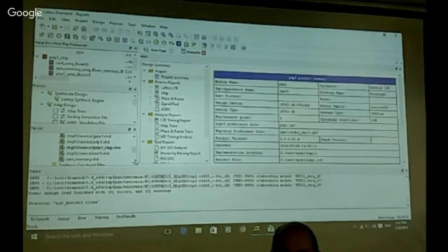For one thing, look at the instruction set. It has a memory increment, and it has a memory increment and skip positive instruction. These are very nice instructions, but I need decrement. It does not have a decrement instruction. So I have 4 empty slots, so I put in the decrement and then decrement skip positive. That's for the loop.